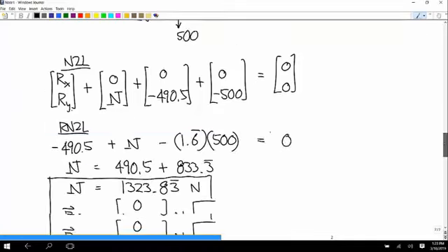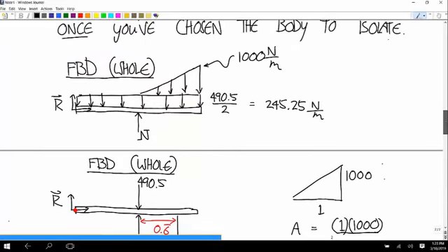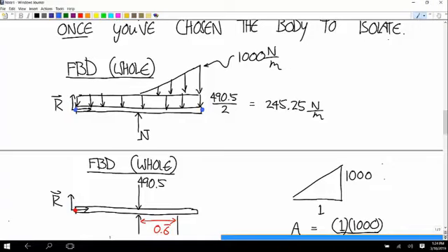All right, so now we're going to the cuts. Where do we have these key points is the question. Endpoints, first of all, there's an endpoint, there's an endpoint, and now places where you have point loads, there's one, and now places where distributed load functions change.